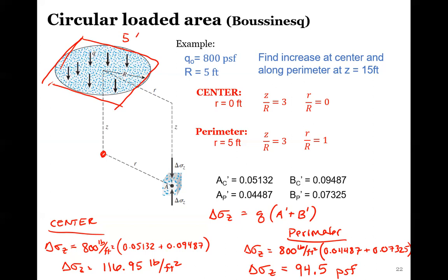But if we actually have a very sensitive project, again, like the power plants, the dams, the things that are supposed to last for decades, Amazon facilities, that kind of stuff, then we would always want to do some type of field verification. So actual numerical modeling or actual stress plates, sensors in the ground that can actually measure the loading, to ensure that our analytical estimates on paper are what they actually are in the real world. So it's always going to be based off of the project that you're working on.